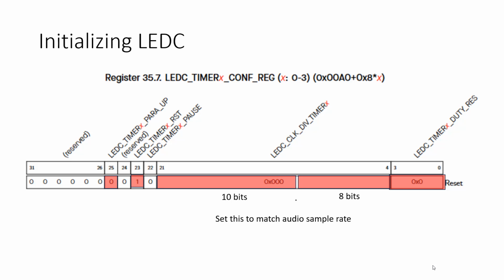Yeah. So if you open up a WAV file, each sample, actually nowadays really high quality audio uses floating point numbers for the samples, but we want to use just 8-bit integers. So the duty resolution is essentially what width value the hardware is expecting for you to put in as the duty cycle. In this case, 0 to 255, which represents a duty cycle of 0 to 100% on the PWM signal.